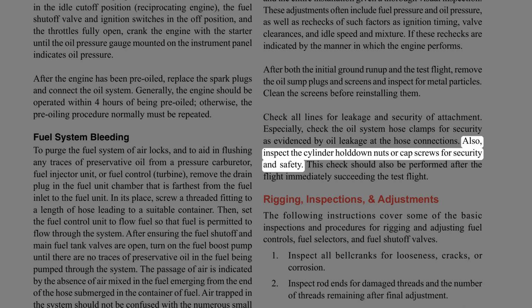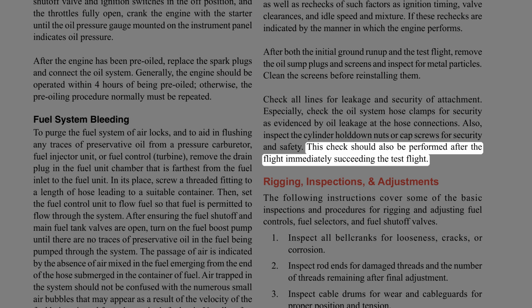Also, inspect the cylinder hold-down nuts or cap screws for security and safety. This check should also be performed after the flight immediately succeeding the test flight.